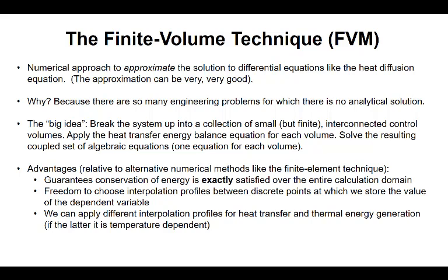The finite volume method has a number of advantages relative to alternative numerical methods like the finite element method. One advantage is that the finite volume method guarantees conservation of energy is exactly satisfied over the entire calculation domain. This is an advantage that is incredibly important when solving heat transfer problems. Another is that the finite volume method allows freedom to choose interpolation profiles between discrete points at which we store the value of the dependent variable. In heat transfer, the dependent variable is temperature.